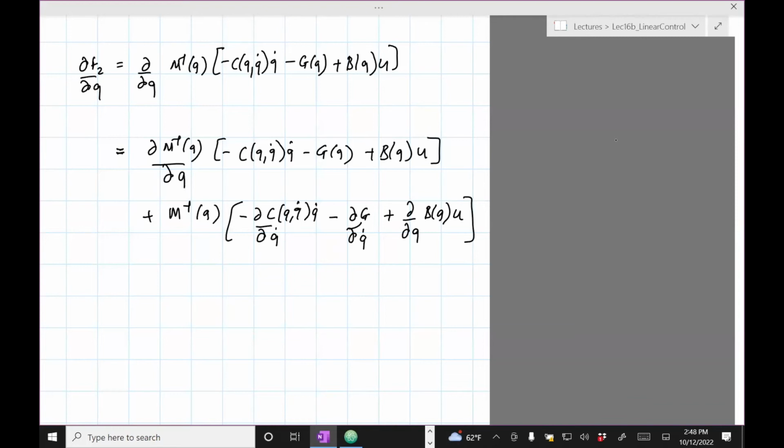Okay, that first term in there is actually a big mess because the mass matrix is usually nice in terms of how it looks because there are cosines and sines. But the moment you take an inverse, you remember in the inverse, you take 1 over the determinant of something that has cosines and sines. And when you take a derivative of something which is 1 divided by cosine, it's a whole big mess. So what people do is they don't really take the derivative of M inverse with respect to q because it's not computationally very efficient. Instead, they do the following trick.